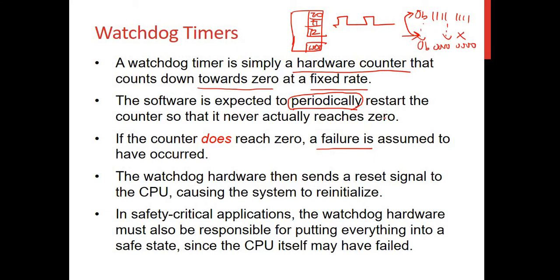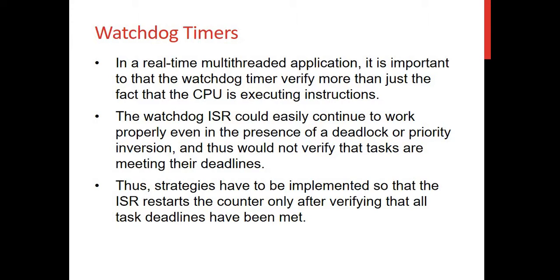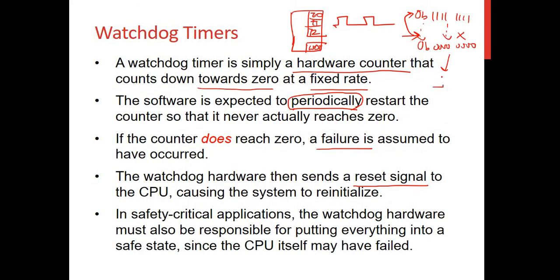And usually what happens in general microcontrollers is that the watchdog hardware has the ability to send a reset signal to the CPU. Most microcontrollers can automatically generate a reset pulse to the microcontroller the moment you hit a countdown to 0.